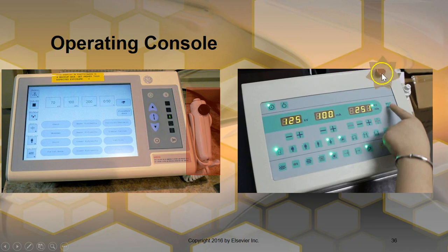right here, I want you to notice that big red button. And with the two things here that's the emergency button. So if for some reason something went wrong with your equipment and you need to turn it off quickly, you hit this big red button. So nowadays they actually kind of cover it with something so people don't accidentally hit it, because if you did, then you've kind of killed the machine. You're going to have someone come back and reset it and all that good stuff.